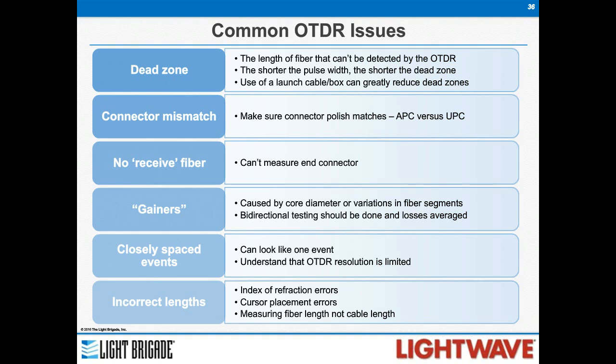And also remember that fiber length and cable length are different. You're measuring the fiber. In many cable designs, particularly higher fiber count, loose tube outdoor cables, those cables are stranded, so there's more fiber in that cable than there is cable. So you have to adjust for that as well.